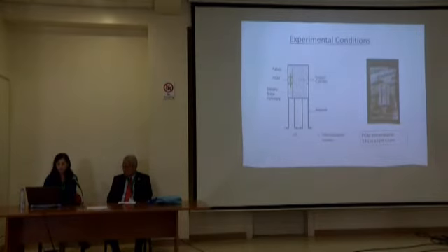So this is a schematic of the experiment. We can see the heated cylinder, and I've used three metallic cages: an outer metallic cage in order to hold the outer fabric, and the other two cages in order to squeeze the PCM. By this configuration, we can see that the PCM is trapped between the macroclimate air layer and the microclimate air one, and this is what the model assumes. This is the PCM that I've used. It's 13 centimeters by 7 centimeters and 1 centimeter in width.